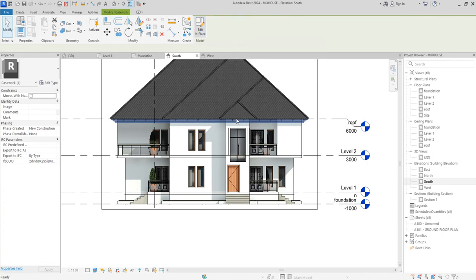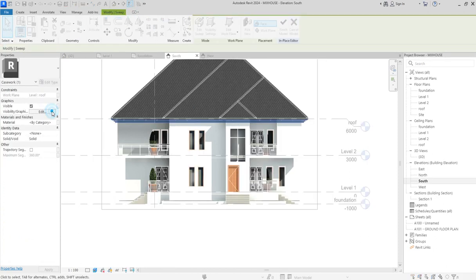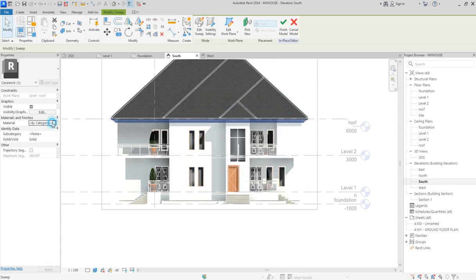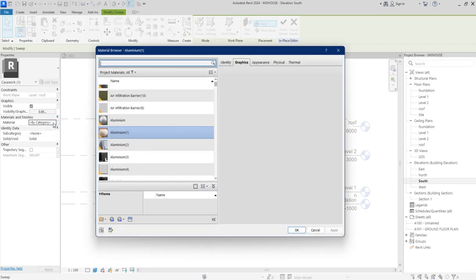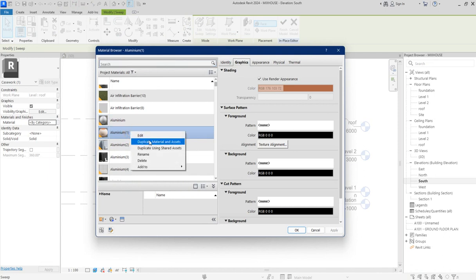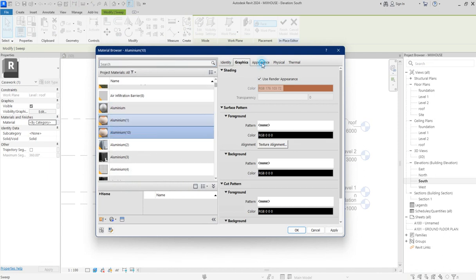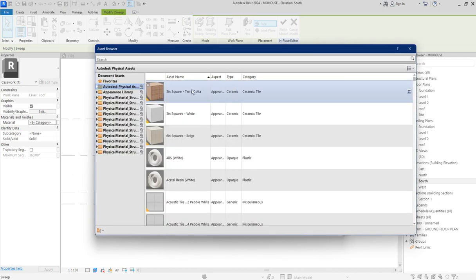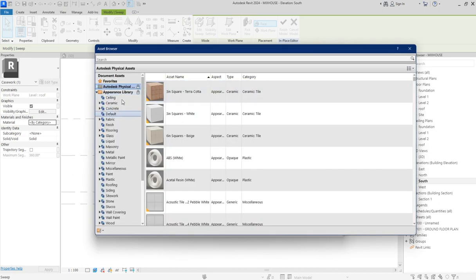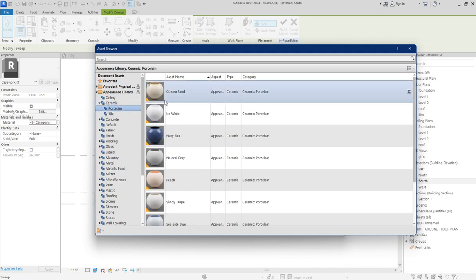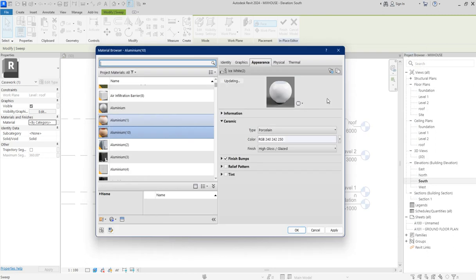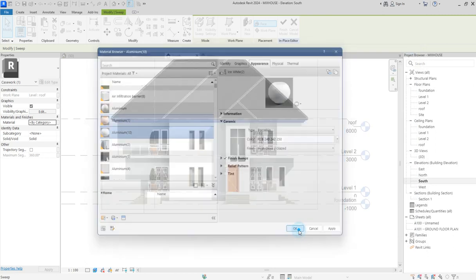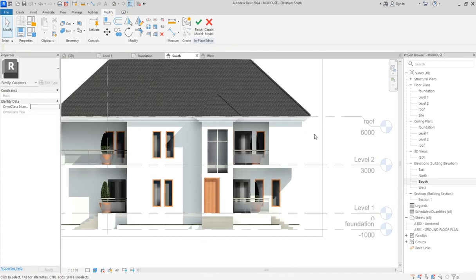Then I want to change the material for the facial. Click here, edit category material. So you select that. So here you duplicate and say duplicate. From the duplicate, here is material, you change the material completely and come here and select ceramic, from ceramic porcelain, and change to ice white. The ice white is okay for me, so the moment that uploads, we accept it, then we move to the next thing, and that is what we do. So this one is done here.